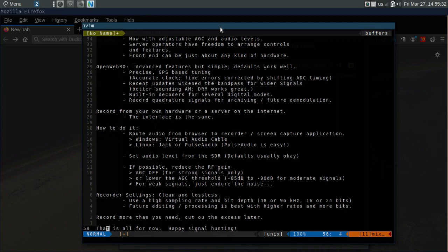If you can bring the low end down to 100 hertz and the top end up to maybe 3,500 or 4,000 hertz, that's a bit easier on the ears. If you're listening to some of the high fidelity single sideband people in the amateur bands, you can go all the way down to 20 hertz. And there's audio to hear down there.